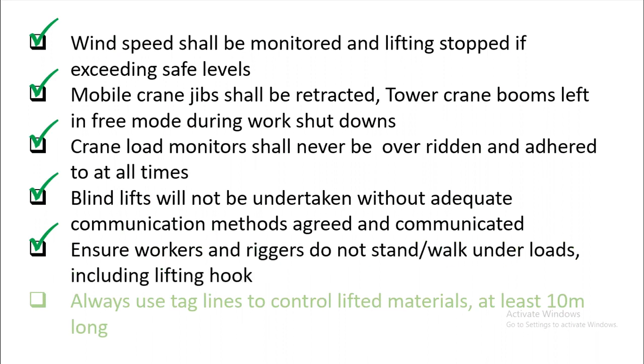Ensure workers and riggers do not stand or walk under loads, including lifting hooks. So when we have suspended loads, or if the crane is on standby mode, so the lifting is suspended in the air, make sure that no workers are passing by below, or riggers standing by below that hook or that load.